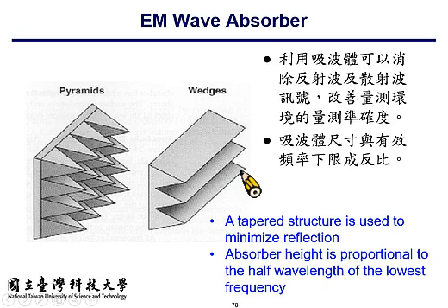Because of the doping conductive particles, the conductivity of the absorber varies gradually as you propagate into it. If you are at the tip, the effective conductivity is small. If you are at the bottom, the effective conductivity is larger. So it's very similar to the so-called taper transformer.